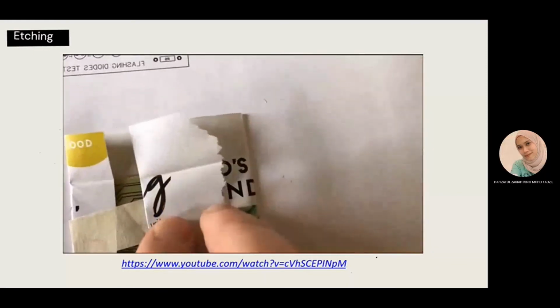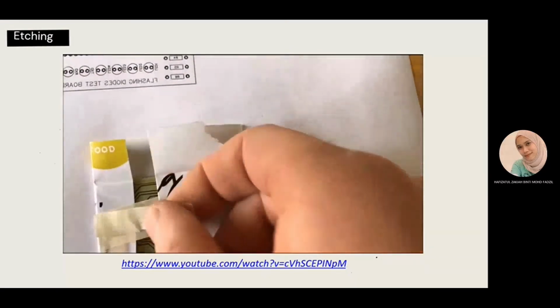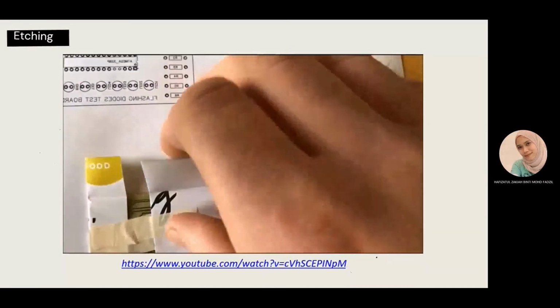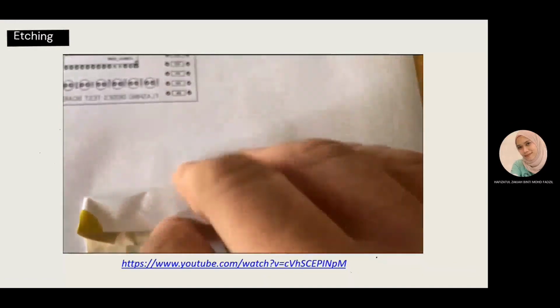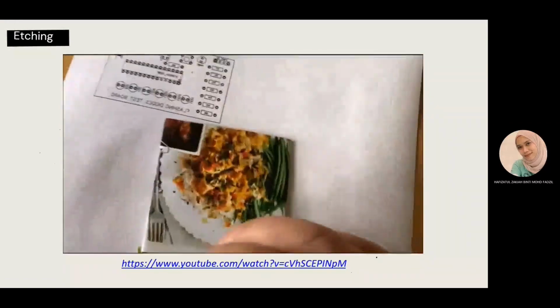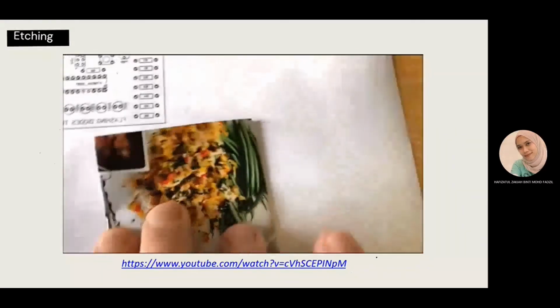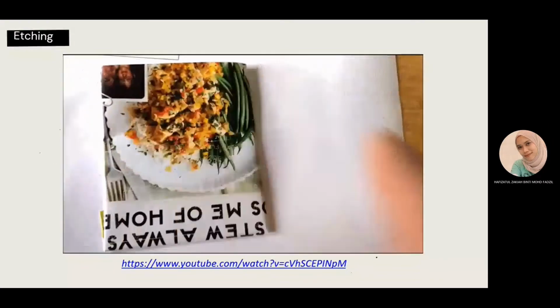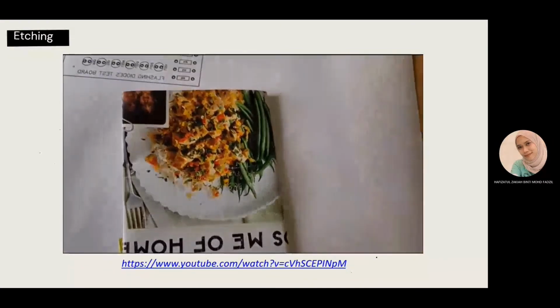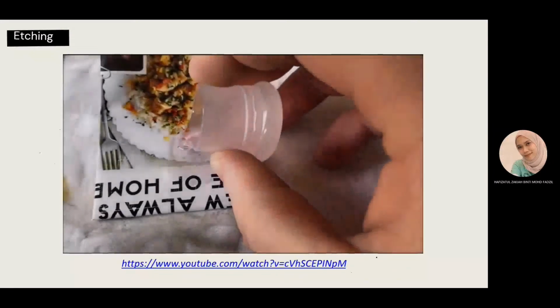So all I've done, on double-sided boards, I've never had a problem, to be honest. By the time the copper's etched away, it's been a rough fibre board. But on single-sided boards, I've had to just roughen it up slightly with a bit of wire wool, just give it a bit of a key, to be honest. So let's place that in there.